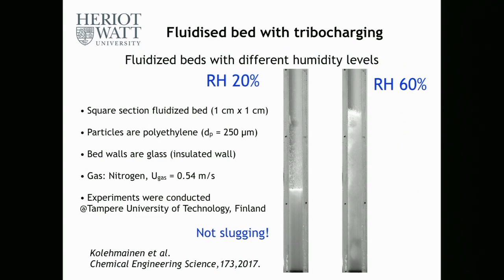So this is our flow configuration. It is much simpler than the example I just showed in my previous slides. Here is a fluidized bed. What is a fluidized bed? We have a vessel and we pour the particles in this vessel and we inject the gas at the bottom. If we increase the gas velocity at the bottom, the particles get agitated and they leave solid state and they behave like a fluid.